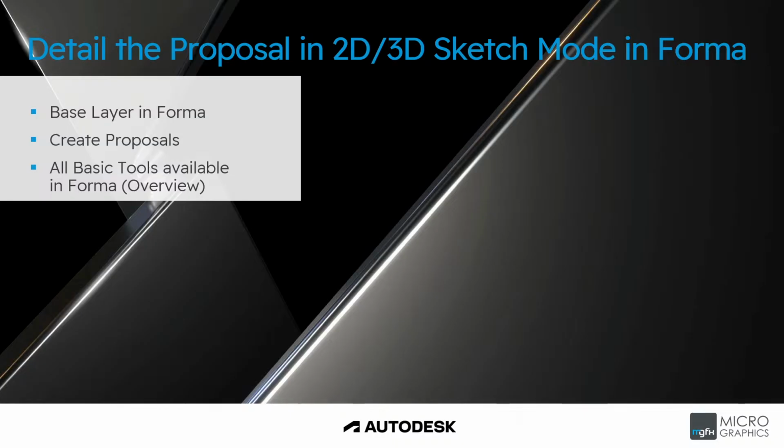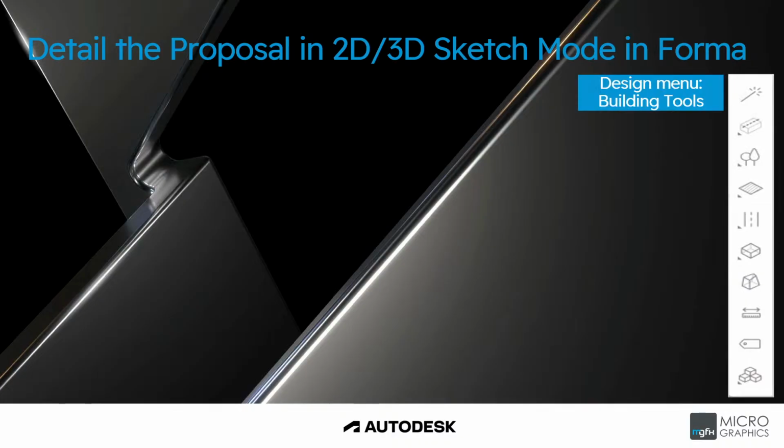Detail the proposal in 2D or 3D sketch mode in Forma. With the data used for your base layer, you can now create your proposal with the tools provided by Forma. Create proposals with the building tools available in the design menu. This is just an overview of what is available. With each of these options, there are additional settings and parameters that can be defined.